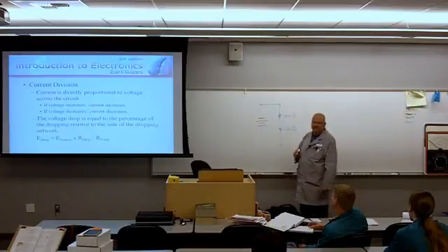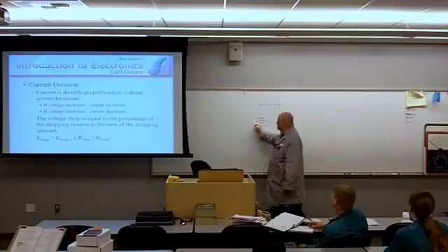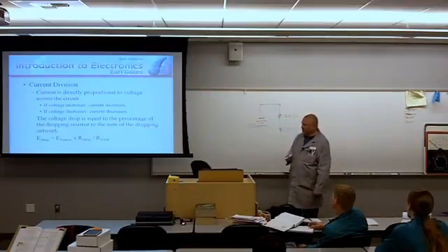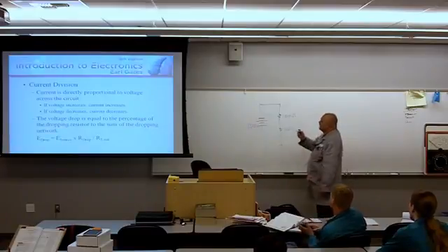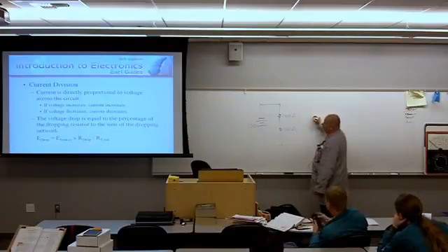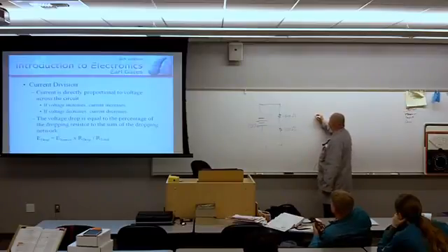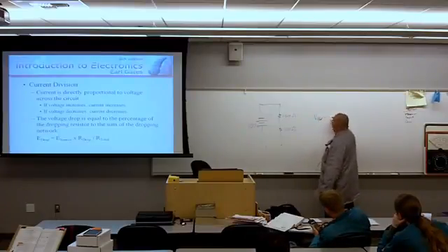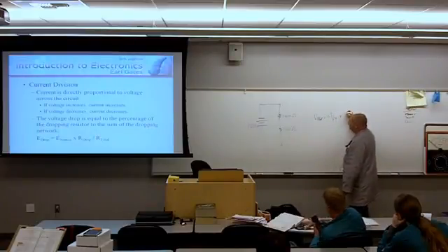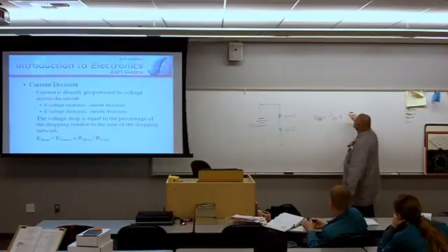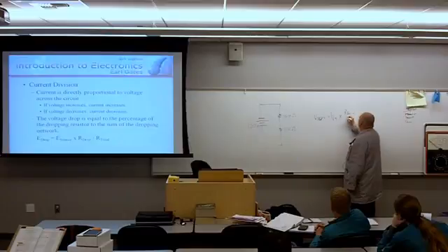this, if I've got this, and I've got 100 volts, let's keep this real simple. Okay? What this formula is showing me is what is our drop here: V drop is equal to voltage total times R drop over R total.